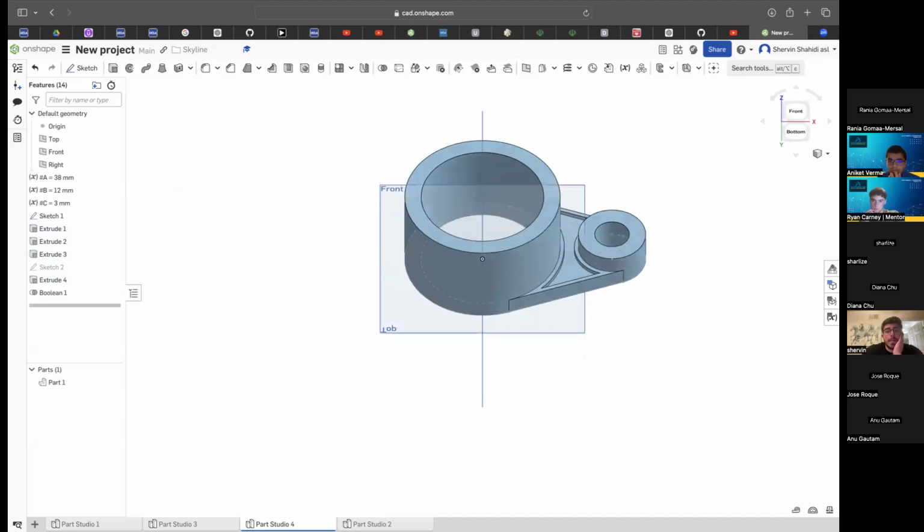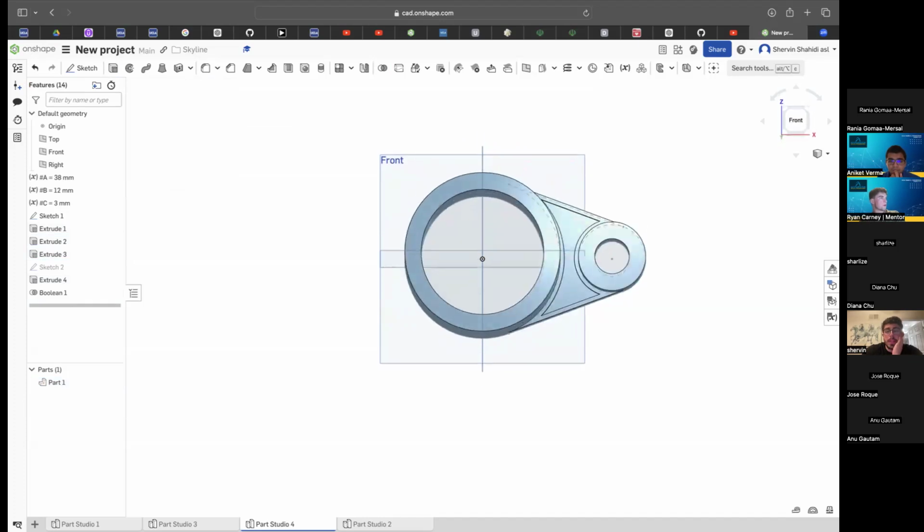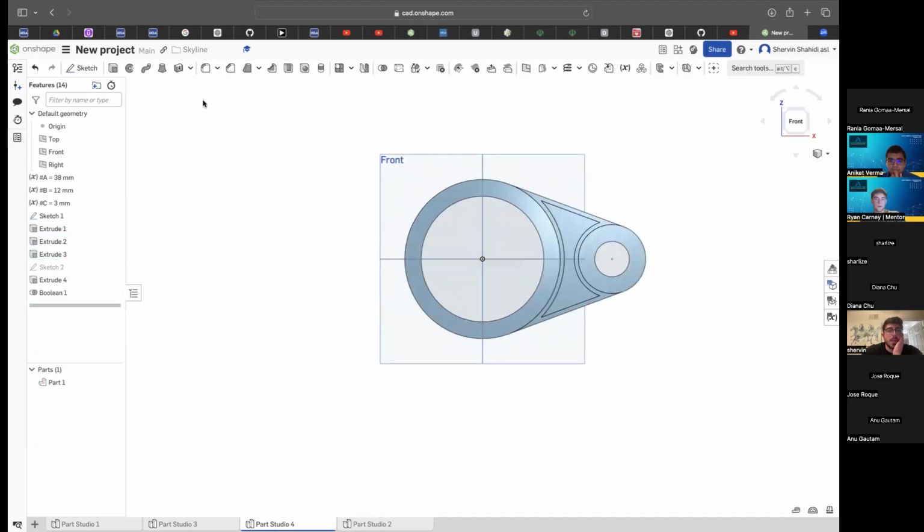Okay, so for mirroring it, I just need to do the same process, right? Yep. So just go to the mirror tool. So I have to click on one of the sketches or? Nope. Just the mirror tool, I think. Oh, the thing is this, right? Yep. And for entities to mirror, you just want to mirror the part over itself, right?